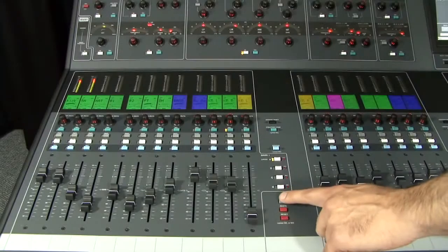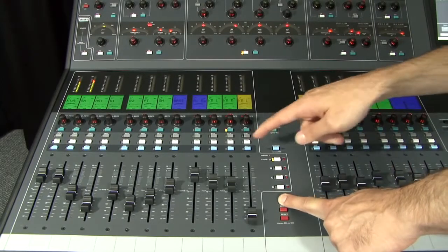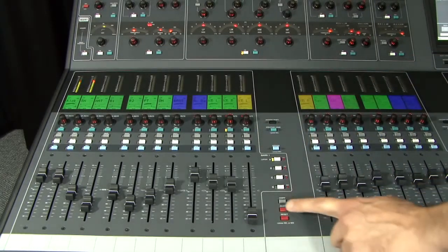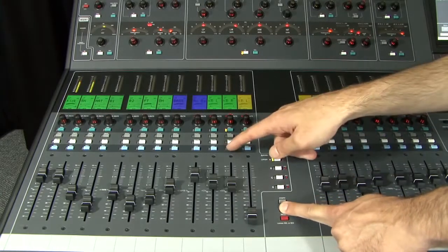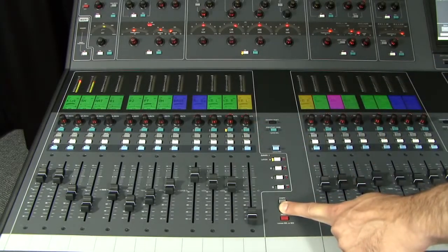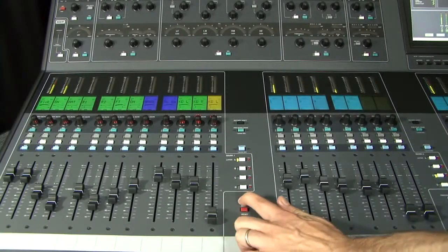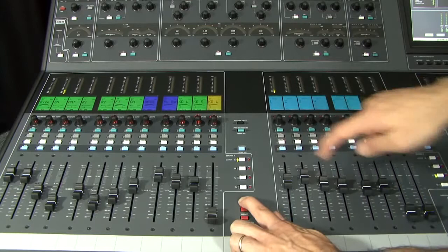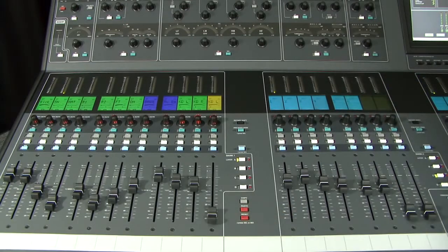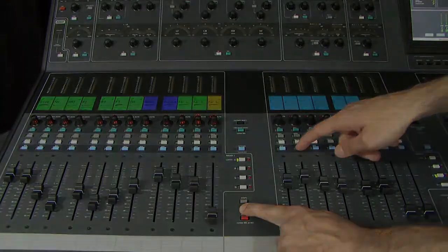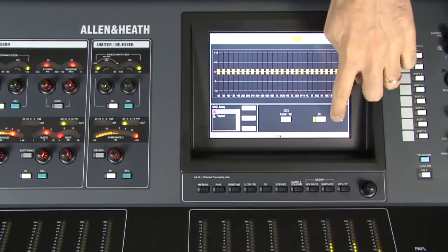Pressing a channel mix key copies the mix settings of the channel including send levels, stereo send image, assignments and pre-post settings. It does not copy the fader and mute settings. Pressing a master mix key copies the whole mix including all channel send levels, stereo send image, assignments, pre-post settings and global send source. To copy the GEQ, use the screen select buttons.